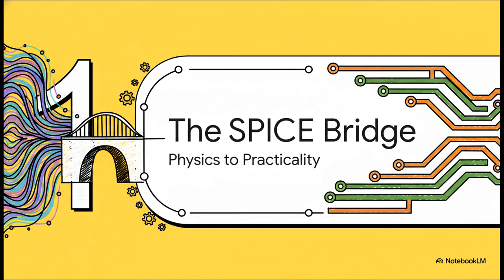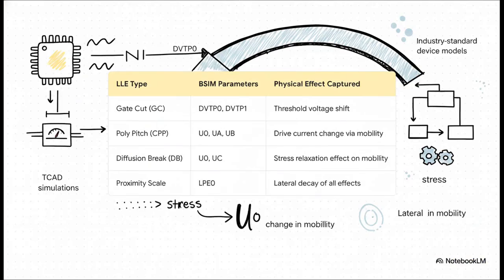You build a bridge, a way to translate all that complex physics into the fast, practical language that circuit simulators like SPICE actually speak. And this table is brilliant. It shows you exactly how that bridge gets built. The engineers literally map the physical effects they see in those slow TCAD simulations directly onto specific parameters in the fast models. So for instance, when stress changes the drive current, that gets translated into a number for the U0 mobility parameter. Or if the turn-on voltage shifts, bam, that becomes the DVT P0 parameter. All that deep physics gets boiled down into a practical set of numbers.